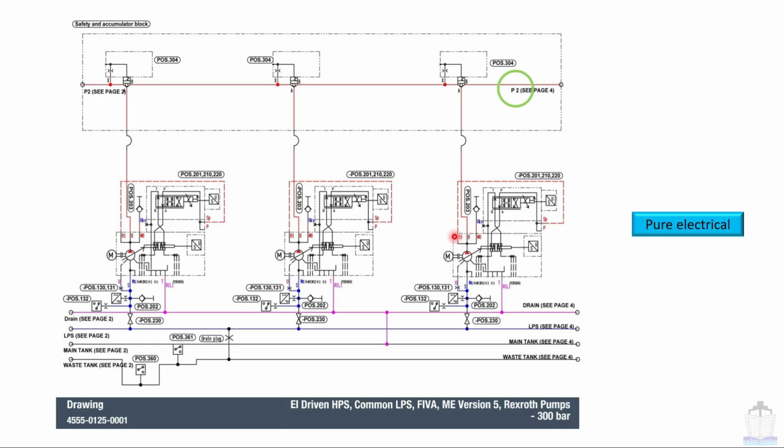So you can see here from point B1, one line is coming and going into the point SP. SP denotes the sensing point, that means it acts as feedback. This channel number 70's job is only to set the desired pressure, and with the help of this SP and B1 point, this swash plate pump maintains the desired pressure. I hope this is clear.